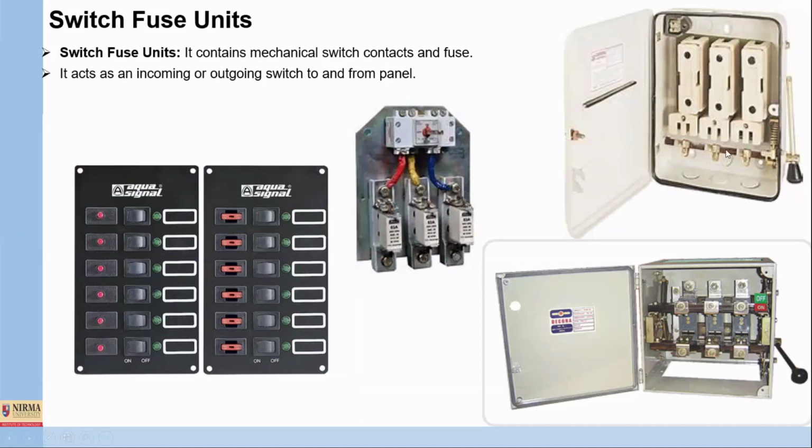And if you are going for three phase supply, definitely for 3 lines we require 3 fuses, so this will be available. But this is not reliable, because when there is some unwanted situation, some overcurrent will be there. What is inside it? There is a fuse conductor, and that is a low melting point metal. What will happen if there is high current flowing through the circuit, or any short circuit on the load side? It will draw more current. Because of that, I square R T amount of heat will be produced, and this will reach the melting point of the conductor, and this conductor will simply melt down and isolate the circuit.